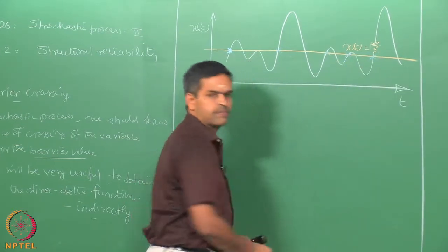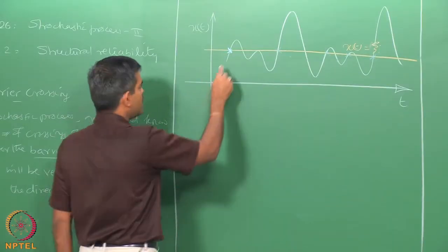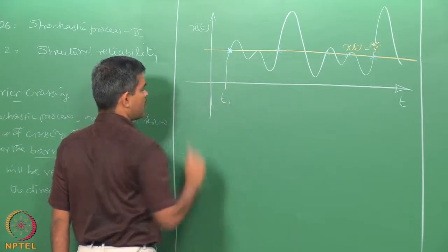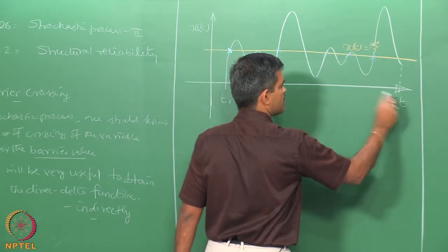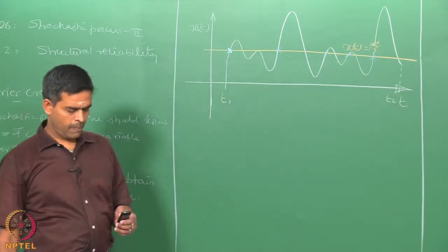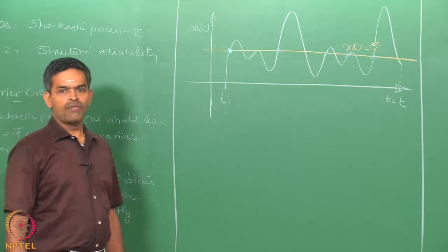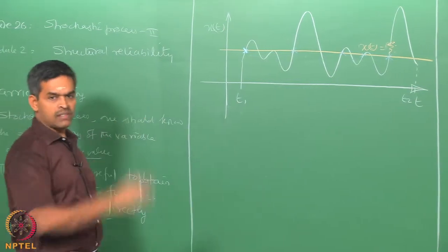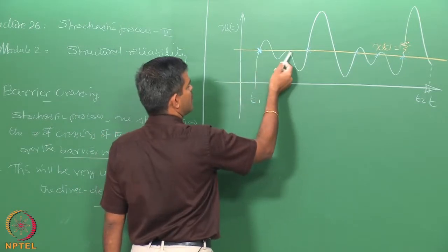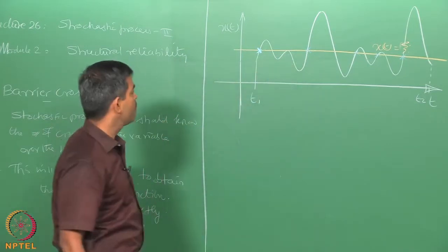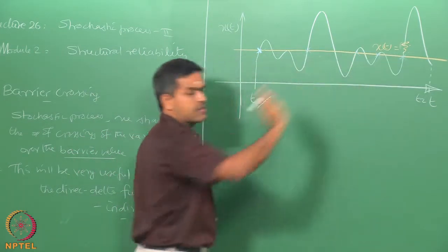Let us say we start the signal varying from the limit t1 and the signal ends at the limit t2. Now, to solve the problem of estimating the expected number of positive passages, why is it called positive passage? I am looking only at the upward crossing. This one is actually not touching the value, so it is not crossing the barrier. I am only trying to mark the upward crossings in the given system.